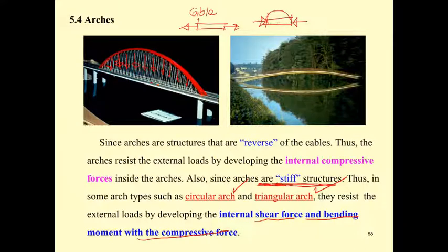So the arch will provide the resistance force, the reaction in the vertical direction, and also it will provide the inward horizontal force to resist the action of the applied forces. It is the opposite of the cable.